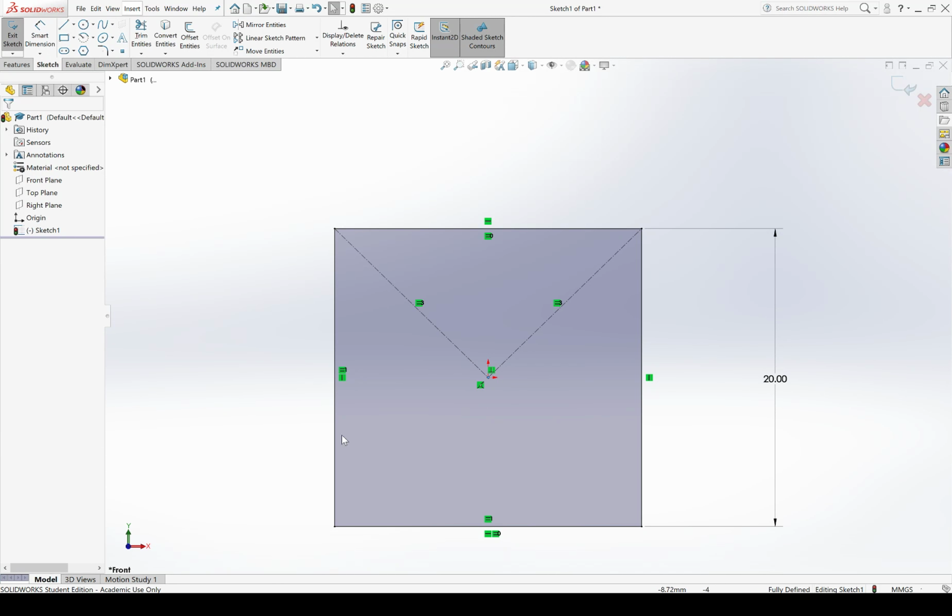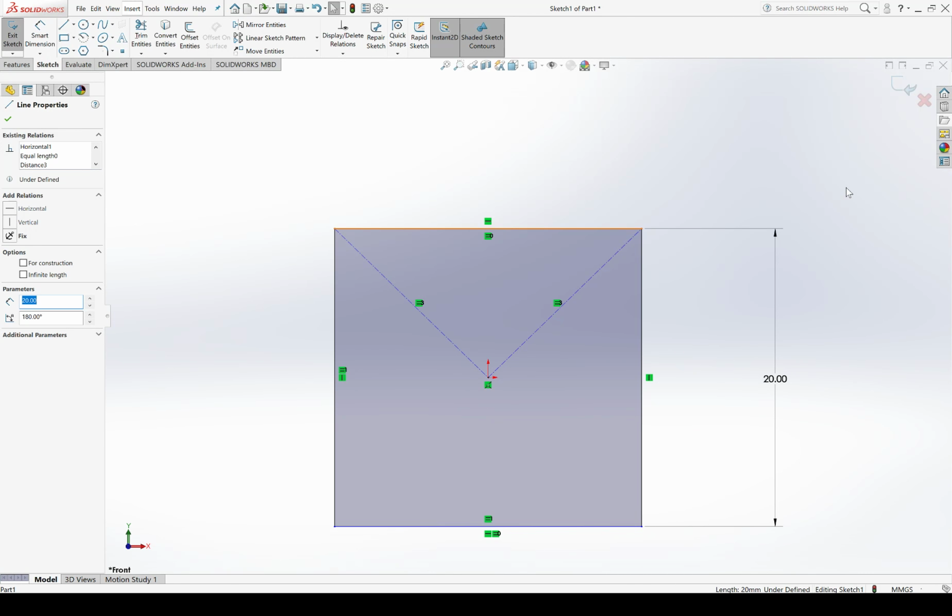Another option. Did you have to say both perpendicular and equal, or did you just say equal length? I could say equal length, but not perpendicular, but if I did that, then I could still move it up and down. Here, I'll show you. If I click on the perpendicular relation and delete it, I can drag the square up, and it will force the origin to be in the center horizontally, but not vertically. What about if you had a rectangle, not a square, you want to say?